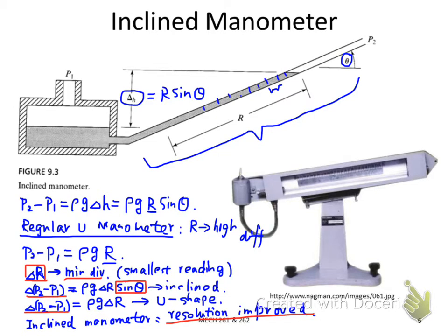So you can see the manometer is a very simple pressure sensor device, and it will not be very accurate because we are relying on visual reading. One more point I want to point out here: in all those measurements, rho plays a role. This is the density of the fluid. So if you have a heavier fluid, you will be able to have a wider measurement range, because for the same height difference, your pressure value will be higher with a higher rho.